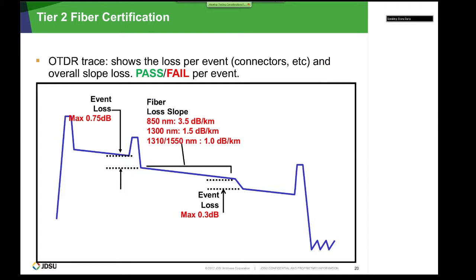Here you can see the optical trace obtained on an OTDR. You can see some reflectances, these spikes, as well as attenuations. Each connector generates a certain reflectance and a certain insertion loss. If you remember, we already spoke about limits: the insertion loss of a connector shouldn't be higher than 3/4 of a dB. Insertion loss of a splice shouldn't be higher than 0.3 dB.